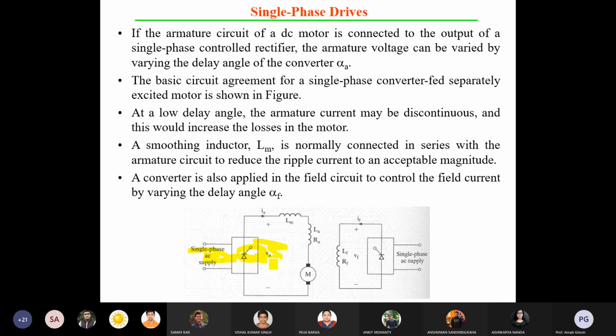Power MOSFETs are normally used for high frequency applications, not high power applications. An IGBT is one option, but the cost of the IGBT may be very high, and this amount of power may not be handled by an IGBT. That's why you have to switch to the IGCT. That can be handled, but they are very costly.